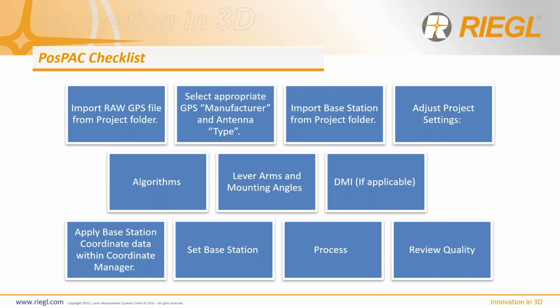So having consistent surveying equipment for when you set up base stations on your own is very critical. And if you don't know the quality of the information that you're getting, do your best to verify it. The sooner you know where your errors lie, the better off you will be at correcting them in post-processing or not having to deal with them at all.